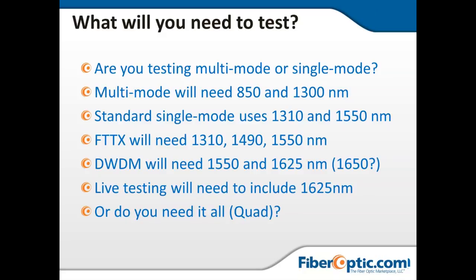But we also want to use this second wavelength as a way of creating a reference for a macro bend. One of the big problems we have with fiber is bending of fiber. We get loss or attenuation, okay? Normally, the higher the wavelength, the better it will perform with fusion splice loss and things of that nature. But it's inversely related when it comes to bending. So the higher the wavelength, actually the more attenuation we'll get when you bend it.